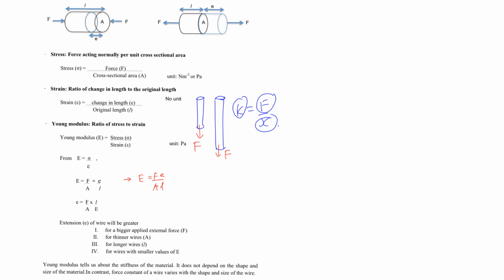Let's look at what is stress, strain, and Young modulus. Now, assuming you have a piece of material here with original length L, you can use compressive forces to compress it by a small distance E, or you can apply a tensile force to cause a small extension E. So we can define the stress, strain, and Young modulus from these two diagrams.